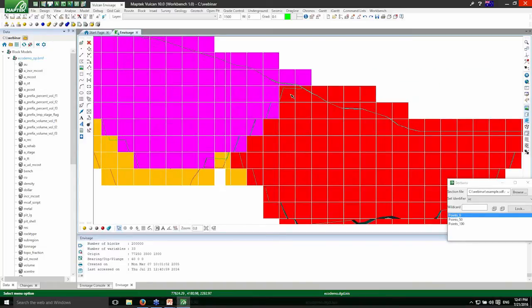All right, so as you can see, in this case, for instance, I got a stage 2, essentially because the volume is 4,400 against the volume in pushback 1, which is 3,500. This is quite simple because it's just two pushbacks sharing the same block. But sometimes you got another block which shares more pushbacks. So in this case, we got three different pushbacks present in the same block, and because the volume in pushback 2 is bigger, then we assign the stage 2.